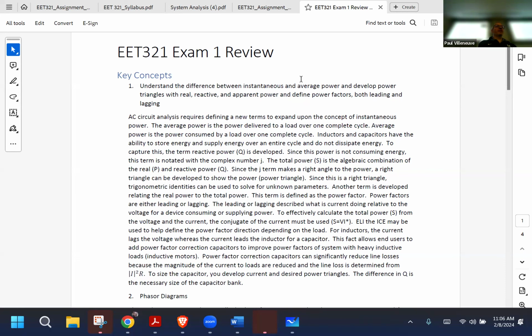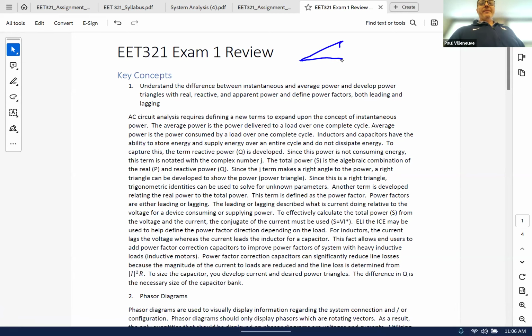For voltage regulation? Well, voltage regulation, the calculation is just based on magnitudes, right? There's no angles. But when you do the current, if you're trying to calculate voltage drops through a system, including the current, then you have to do the inverse cosine to get the angle between the voltage and the current. And it's inverse cosine whether it's leading or lagging? It's always inverse cosine. The reason has everything to do with the fact that it is a right triangle. This is theta.